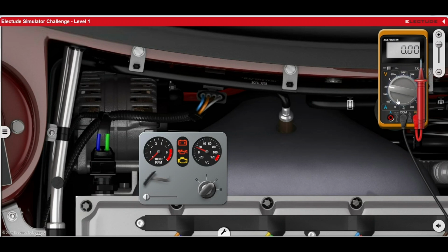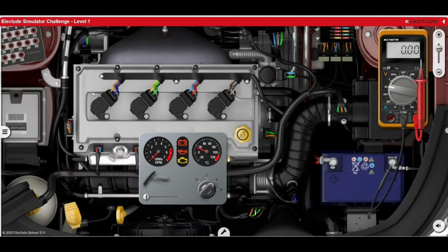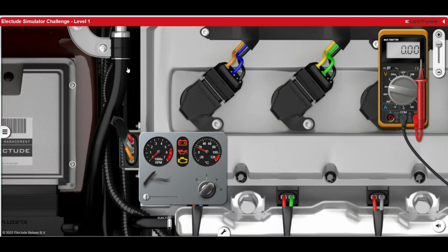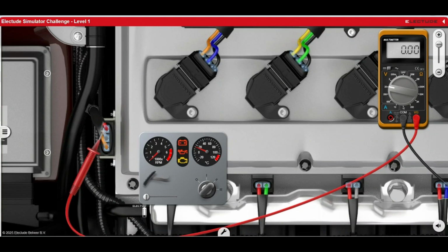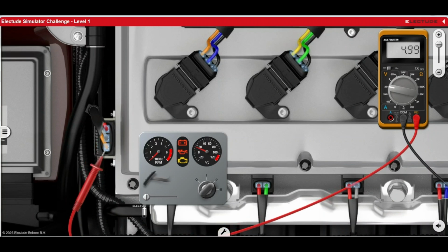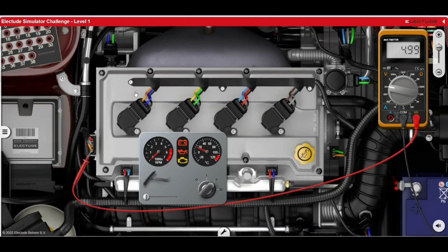Remember, the oxygen sensor is also affected. So I'm thinking of testing at it next. Mind you, all this time I am having so many ideas, so many possibilities, so many reasons in my head that could cause this problem. So I visit the MAP sensor as well before the oxygen sensor. I can see it has the reference voltage, which is fine.